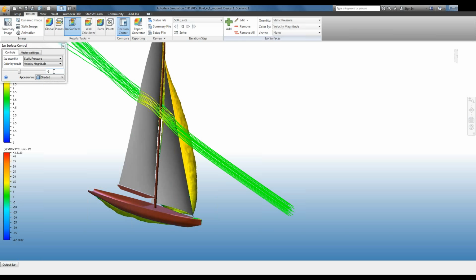We're now seeing the full three-dimensional relieving effects that go on with these sails, and you can't capture that with just a simple 2D. 2D will get you started to let you know, hey, here's a basic shape, maybe as you're doing cross-sections going up the sail, you know, cross-section here as opposed to one here. But don't forget, we're talking about that environment where the velocity down here is very different than the wind velocity up at the top of the mast.